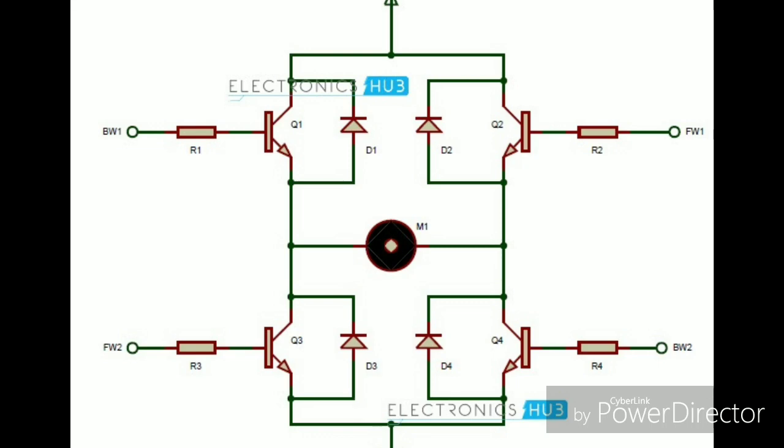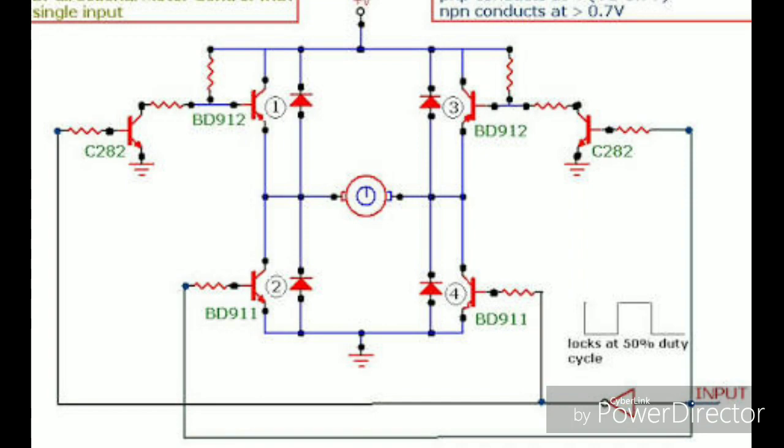In order to drive the motor, the working of the project is explained here, assuming all connections are made as the circuit diagram shows. The pot is connected to the analog pin A0 of the Arduino. This is used to adjust the speed of the motor. The normal operation of the motor is to rotate in the forward direction. When a button, which is connected to pin 13 of the Arduino, is pressed, the direction of the rotation must be reversed and should stay in that direction until the button is released.